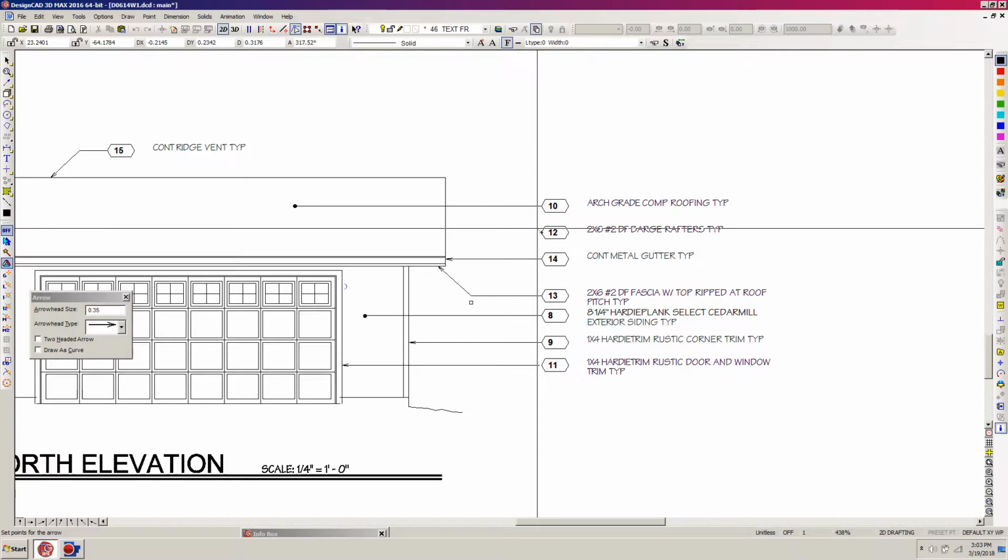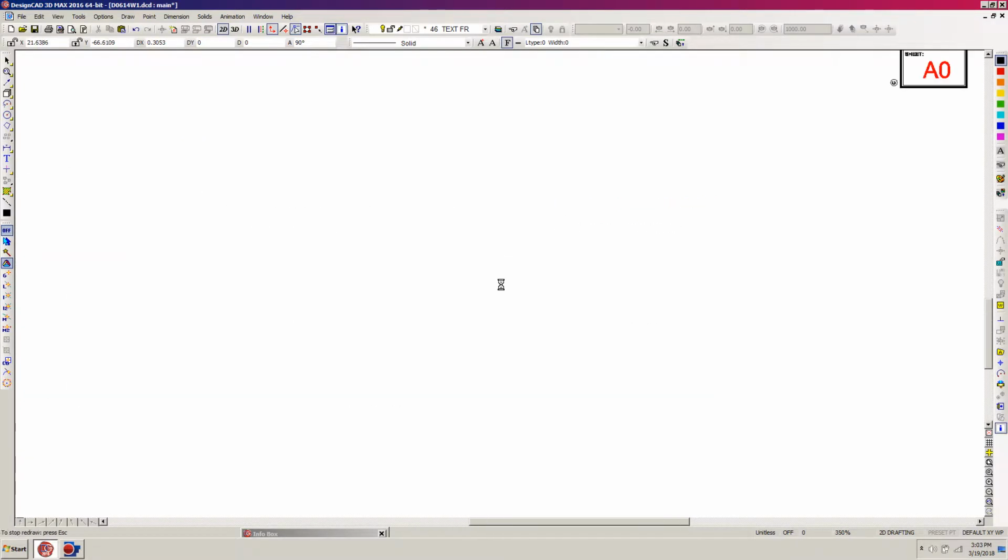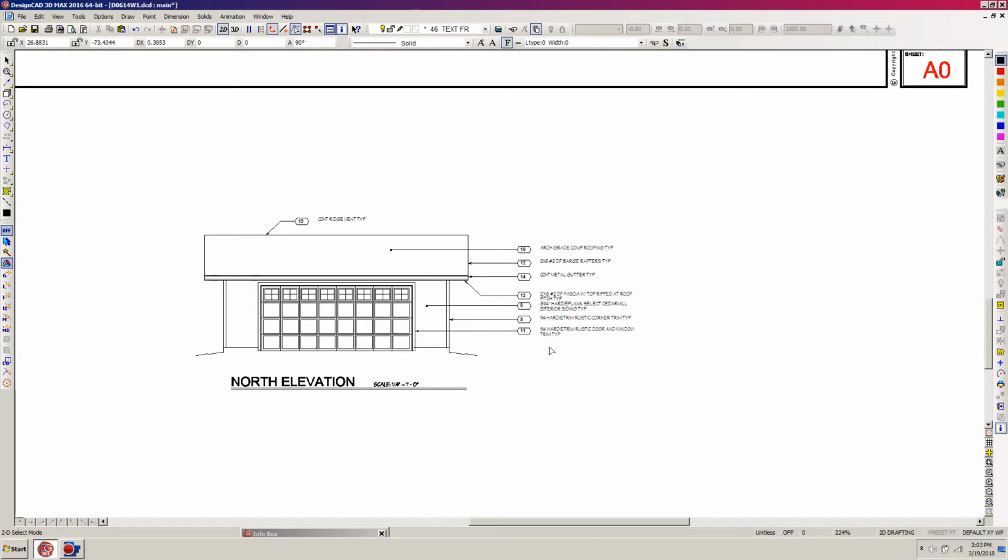Hit escape, arrow command, right click to snap to the end of the point of the sheet note box, H for orthogonal mode, and then K at the end of the roof. And that sets our final note. So in this case, we're going to get rid of all this text in a little bit, but in the meantime, it helps us keep these sheet notes sorted out,